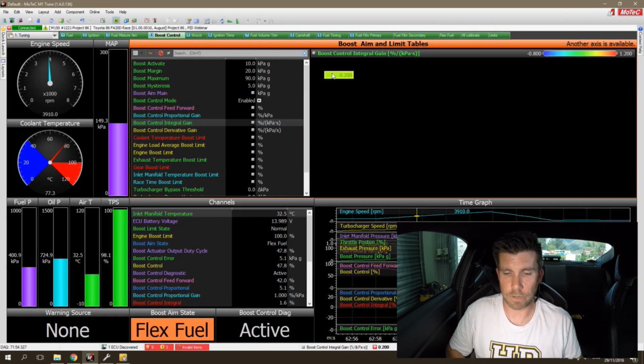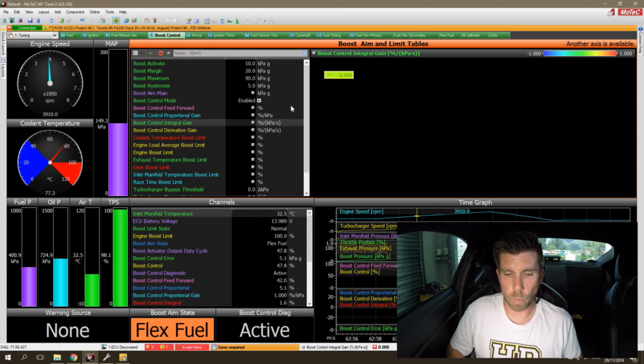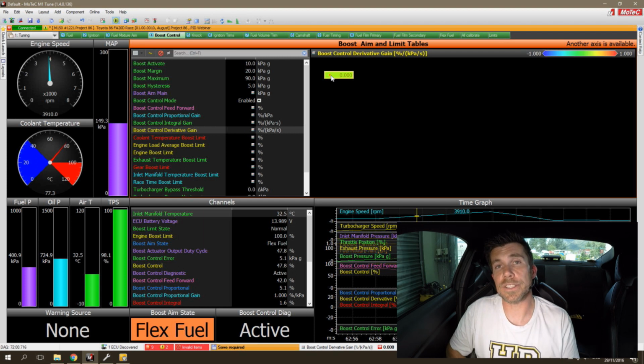Alright, now what I want to do is just zero out these gains for a second, and we're going to have a look at what happens when our gains are set too aggressive. So in this case I'm going to jump up to our proportional gain. In our example that I gave there, we didn't have perfect boost control. It wouldn't have been a great example of closed loop control if it had been perfect off the bat. I really wanted to show you what happens when we do have some error in there.